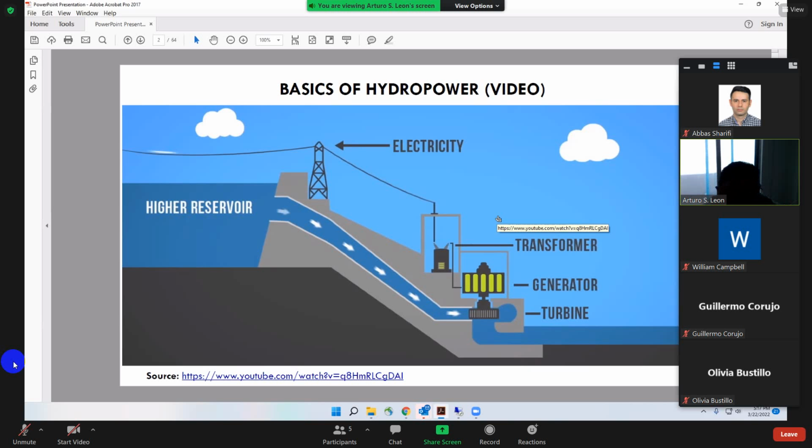However, one of the trends that's happening in the last perhaps 10 or 15 years is combining hydropower with nuclear, with sun power, and with wind, and with other minor forms of power. Whenever you want to maintain the base load, you use the hydropower, and then whenever it's available to offset the variations. So actually hydropower is good for offsetting the variations.